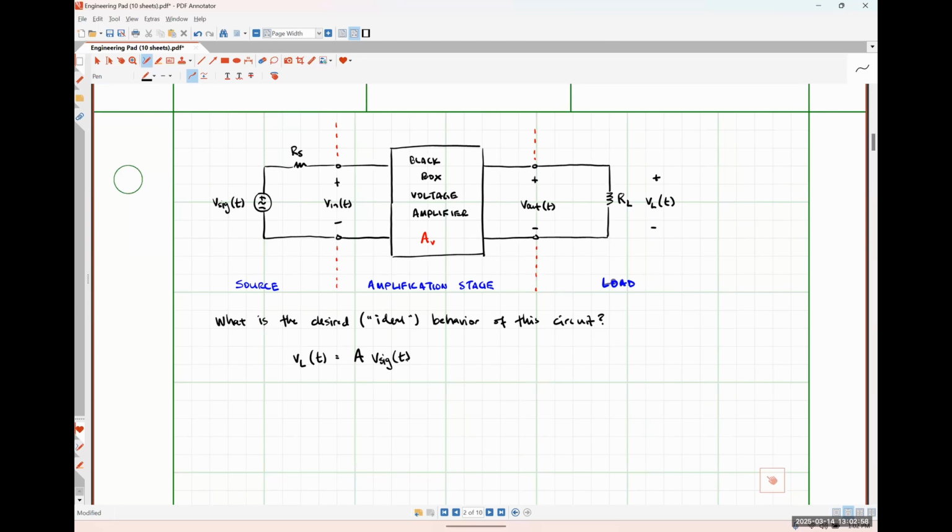The one that we are going to be dealing with is specifically going to be a practical model for voltage amplifiers, but every voltage amplifier, regardless of how simplistic or how complex it is, can actually be characterized by this pretty simple model. Doesn't matter if it's made of 1,000 transistors, capacitors, and inductors, or if it's literally just a single transistor and 2 resistors. Either way, it's going to behave like this simplistic model, okay?